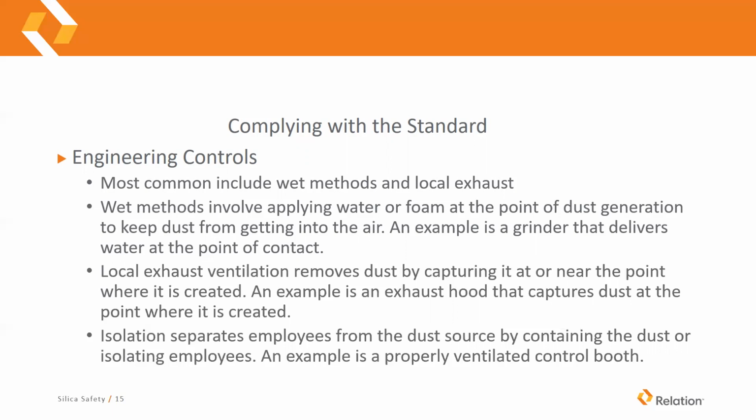Isolation separates employees from the dust source by containing the dust or isolating the employees. So you can either isolate the piece of machinery to keep the dust inside, or you can just isolate your employee in a booth. So those are more of fixed type controls.